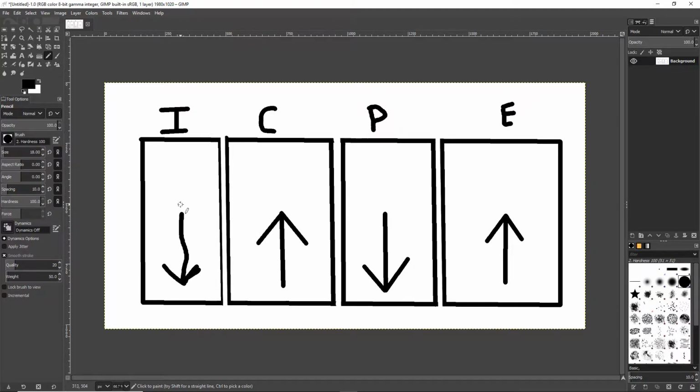So on my intake stroke, my pistons will go down. This is not a 4-cylinder, right? This is not 4 separate cylinders. Let's pretend this is 1 cylinder going through the 4 strokes of the 4-stroke process. So this will work on a 2-cylinder, this will work on a 3, 5, 8, 10, 12 cylinder. It doesn't matter how many cylinders we have. If it's a 4-stroke engine, each cylinder and each piston go through these 4 strokes to complete one cycle. Okay, does that make sense? If it doesn't, write this down. I'll prove it to you on the engines outside, so take notes of this.